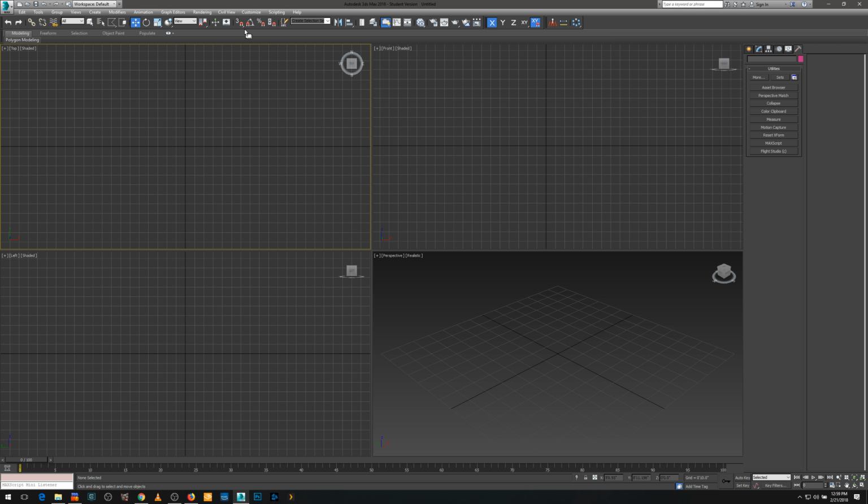I use the measure tool a lot, and these help for movement and snapping. And speaking of snapping, these are your snap options. So this is direction, and this is angle snap. So rather than having 1.289, angle snap, it'll snap in increments of 5. So you get 5 degrees, 10 degrees, etc. For snap toggle, right-click that. It'll bring up your options.